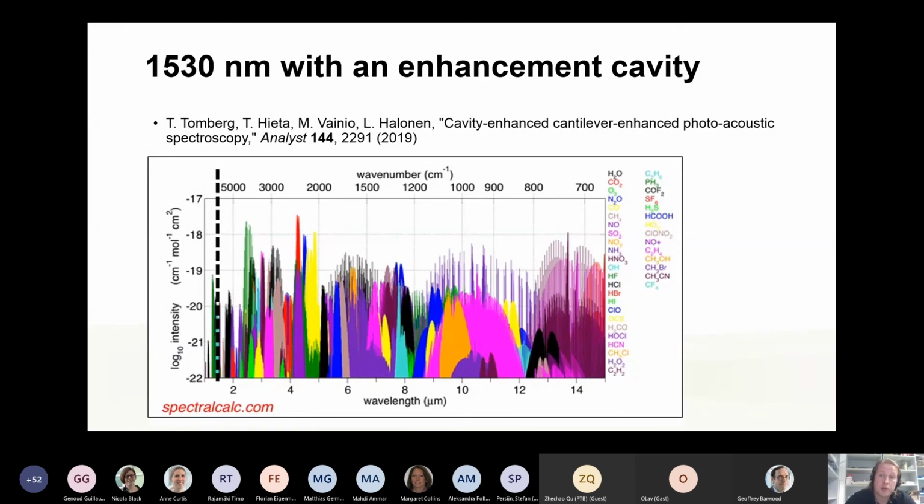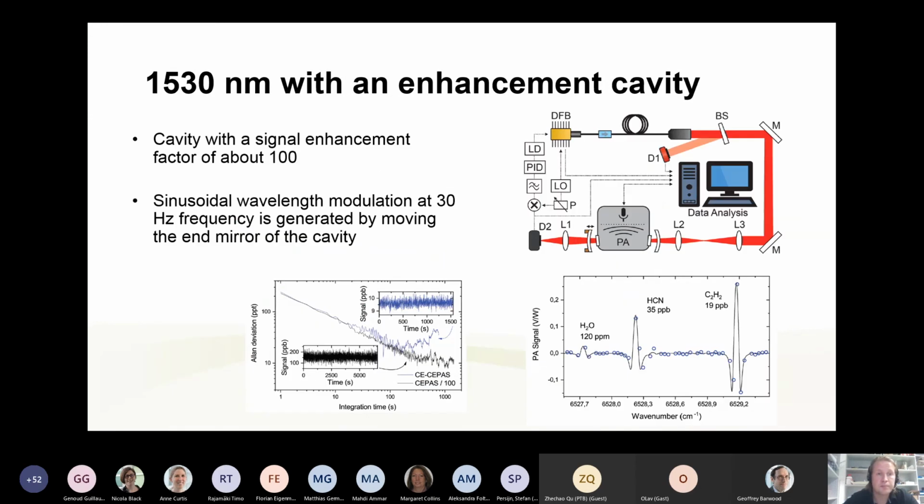This is also the go-to region for many cavity ring down systems, and there are commercial cavity ring down instruments that use this very region to measure several lightweight molecules. The manufacturers are, for example, Tiger Optics and Picarro. The transitions in general in this region are quite well isolated and still fairly strong, definitely enough to enable sub-ppb detection limits.